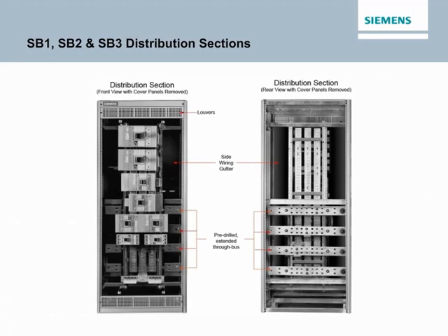All distribution sections contain louvers at both the top and bottom to assure proper operation. Because all distribution sections can accommodate any combination of panel-mounted branch devices, future system modifications are easier to handle without adding switchboard sections. Installing additional distribution sections is simpler because the through bus in each distribution section is extended, and the end is pre-drilled to accept splice plate bolts. The accompanying chart outlines SP1, SP2, and SP3 branch devices.